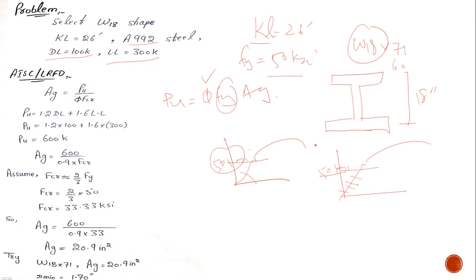So here I don't know what mode of failure would be followed, whether it would be a material failure or geometric failure. So I should not presume that my steel reaches 50 ksi. It may suffer a material failure. So that's why I have to change this Fy into F critical.